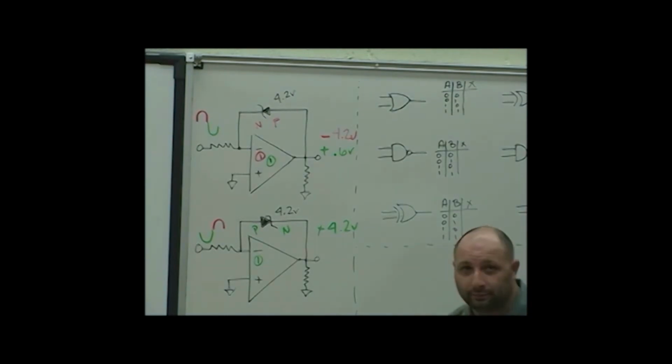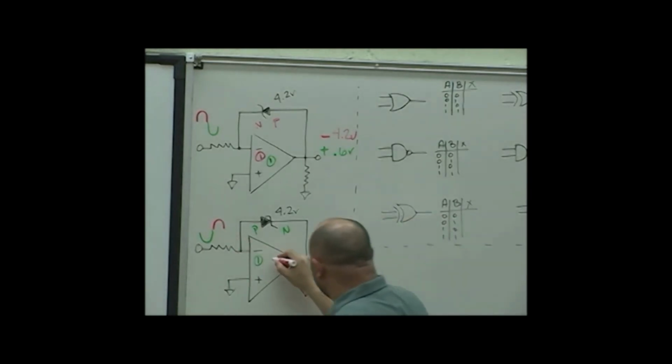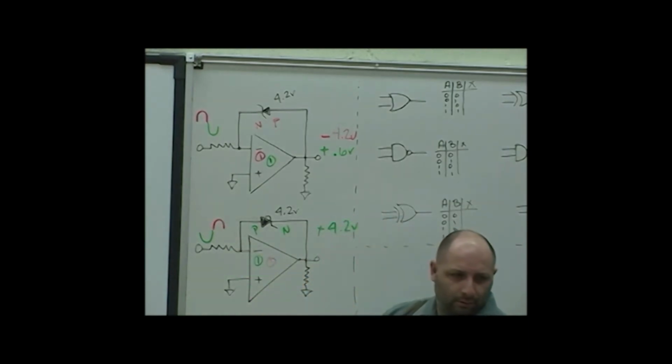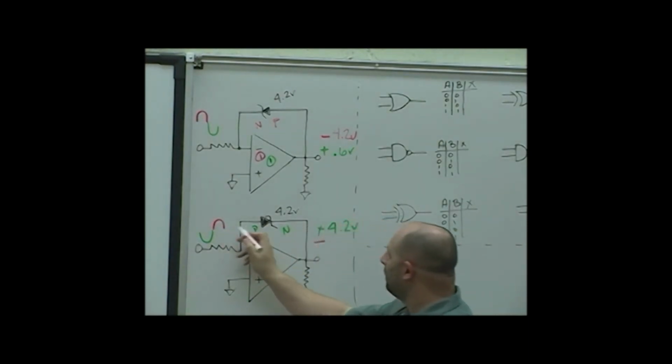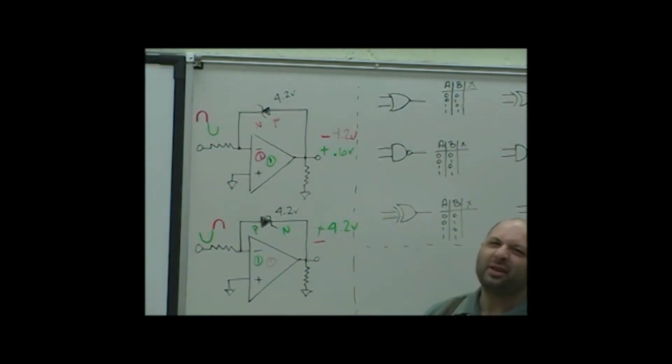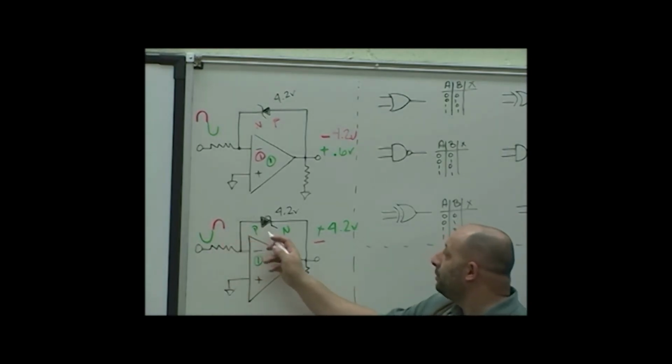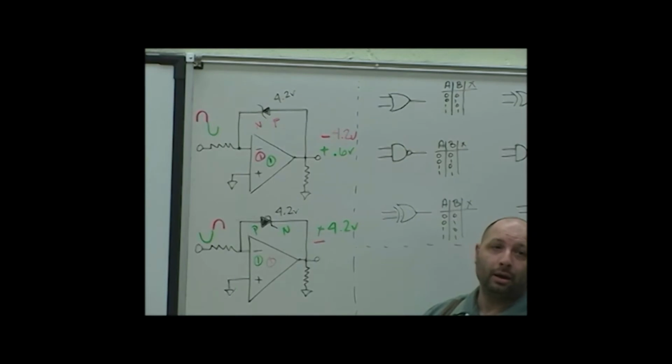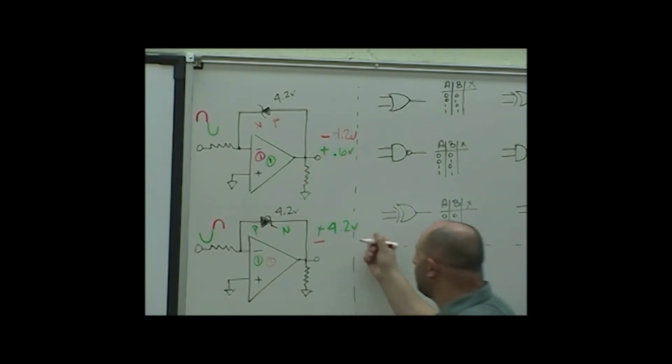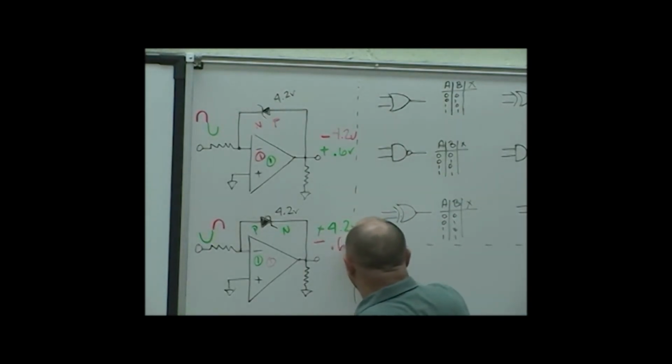Thanks for volunteering. Ready? Just walk me through it. Step one. For the positive half cycle, you're going to invert it, so it'll come out as a negative. Keep going. I'm putting more positive potential on P-type material, and since BU03, that concept, we always say, it's going to be forward. There you go. Because it must be, because we already wrote that down. So it's gonna drop the proverbial, what do we always say? Yeah, 0.6, like that, done.